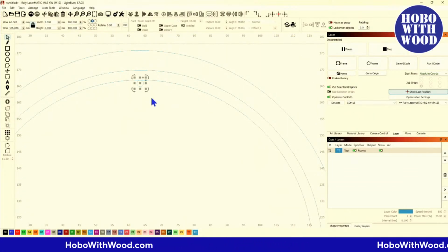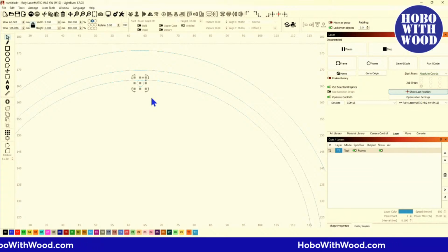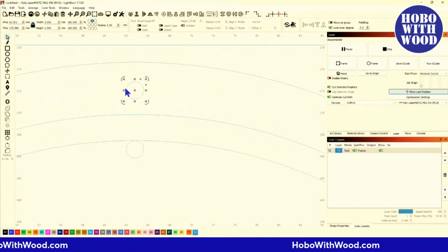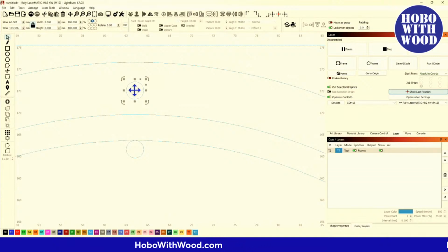Well, I'm going to take this, duplicate it, and come up here. I'm holding my control and arrow button, that was 1/4 millimeter at a time jumping up there. I want to put this where it's going to be creating the least amount of weakness. I don't want it too close to this edge or too close to that one. I want it centered up there. How do I do that?